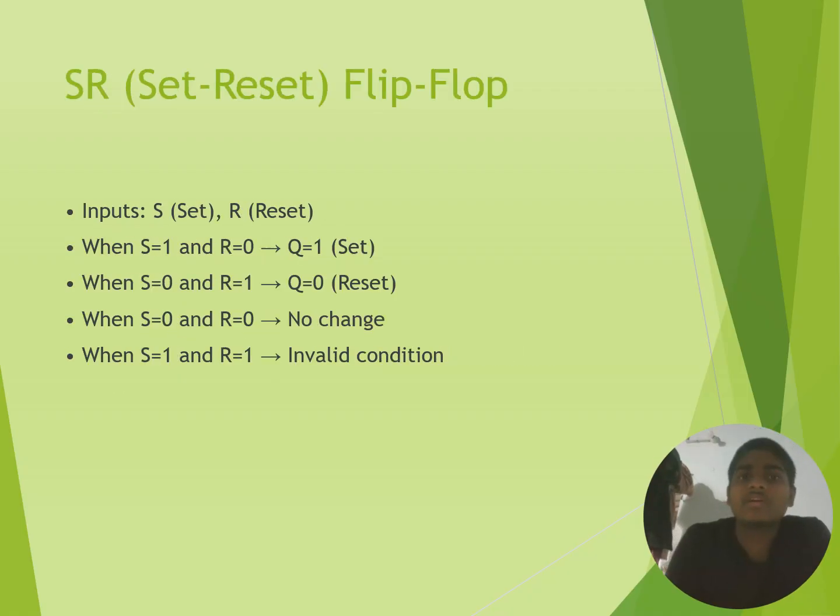First one, SR. SR means set-reset flip-flop. The inputs are S and R. S means set, R means reset. When S equals 1 and R equals 0, Q equals 1. When S equals 0 and R equals 1, Q equals 0, which means reset. When S equals 0 and R equals 0, there is no change.